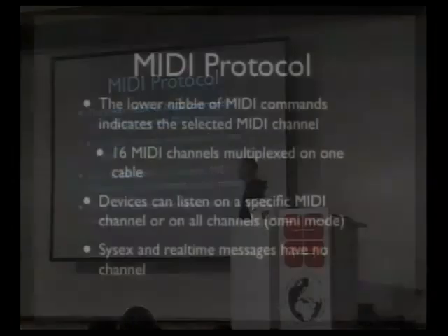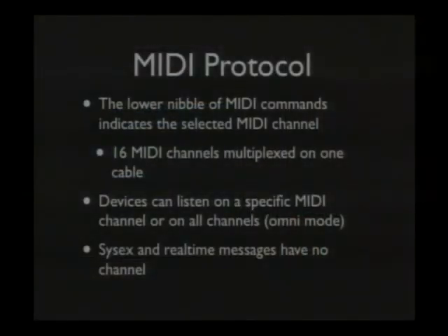On MIDI, you also have MIDI channels, which is another way to multiplex information on this one serial link. You can have 16 MIDI channels on one cable, basically, so you can connect multiple synthesizers and address them individually. The MIDI channel is always encoded in the lower nibble of the command byte, so devices can listen on a specific MIDI channel or on all channels.